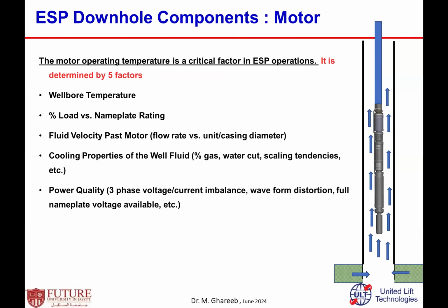What is the power going to the motor? Is it good quality? Is it stable power, for the volt, for the hertz, and so on, or fluctuating, making the motor generate more heat? We usually like the power to be balanced, because the motor is a three-phase motor, there are three conductors, and the power going to each conductor is almost the same in volts and so on, or else it's unbalanced. All that affects the motor temperature.